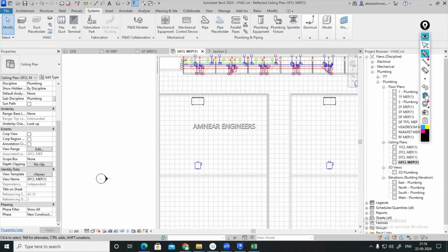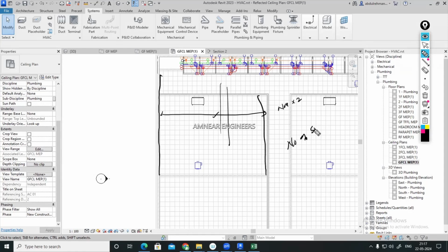So when we were doing it in AutoCAD, within the boundary we made a line and divided it by the number of sprinklers multiplied by 2. The same you can proceed with there, but the easy option is you can create grids and divide by grid. How many grids do I require? Number of sprinklers multiplied by 2 plus 1. For example, if you want to place 3 sprinklers here, then the number of grids or line references you need to divide is the number of sprinklers, 3, into 2 plus 1.